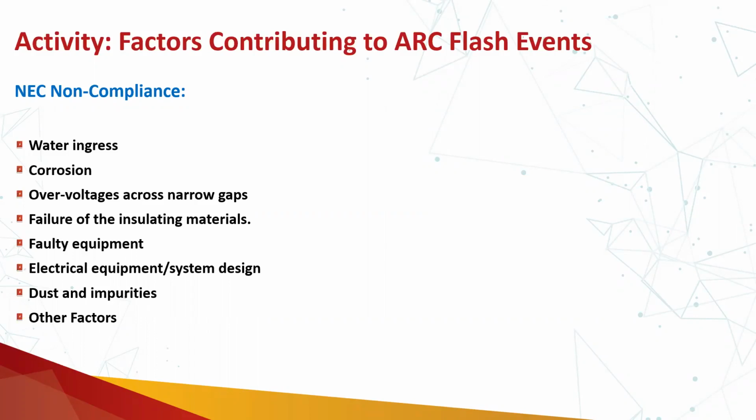If it was an area where there were chances of flooding, or if you are installing some equipment outdoors, it is understood that one day or another, due to raining, or maybe some water pipe failure, that asset might come under flood condition. So why water ingress? It was due to the poor design of the equipment itself or the poor selection.